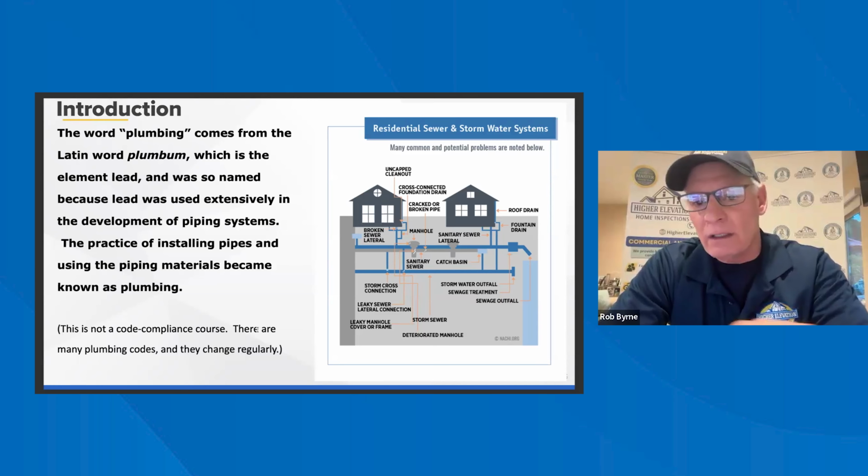Showers, same thing. When we check a shower, we move the head around. You don't want the water to just run into the tub or the shower pan. You want the water to hit as if you were taking a shower and standing in there, with the water bouncing off you, hitting the wall, hitting the glass door possibly, and you check outside for leaks after that.